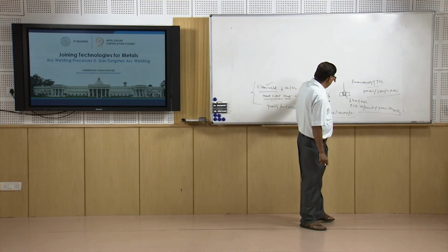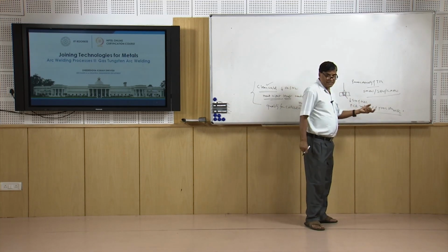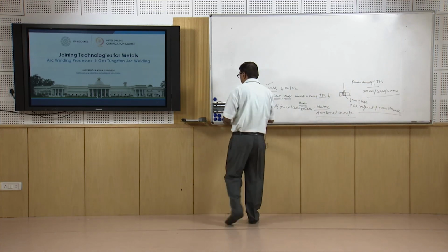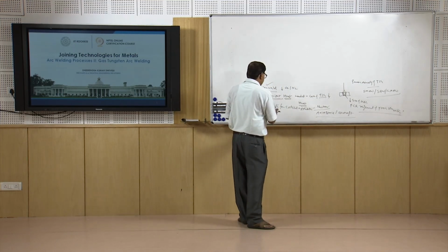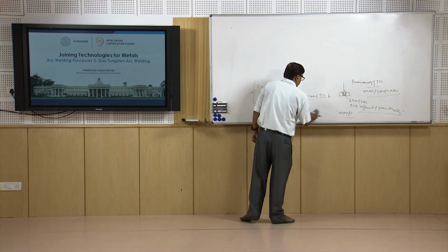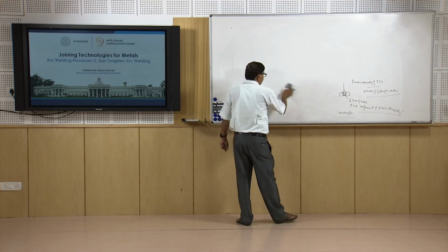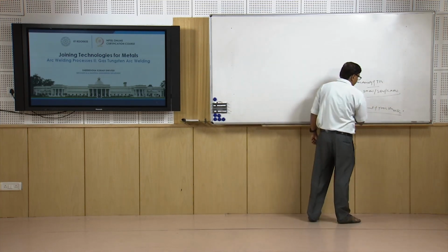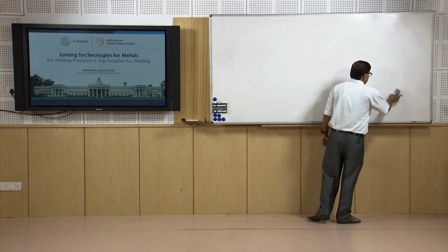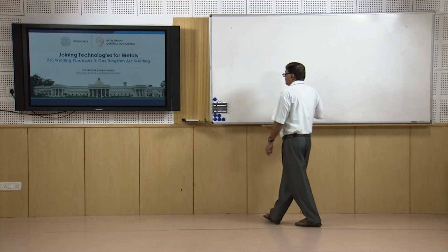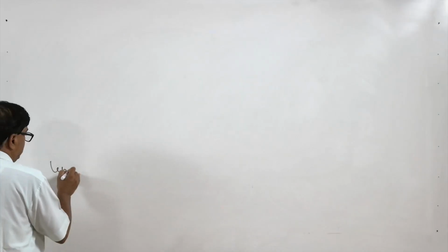The cleaner weld and reduced heat input help in reducing the size of the heat affected zone and give a finer grain structure, and so a much better quality of the weld joint is formed. This is true irrespective of the metal system, whether it is aluminum or the ferrous metal systems, and that is why for all critical applications TIG welding is invariably preferred over the other arc welding processes like submerged arc, shielded metal arc or gas metal arc. But the gas tungsten arc welding process suffers from one major limitation.